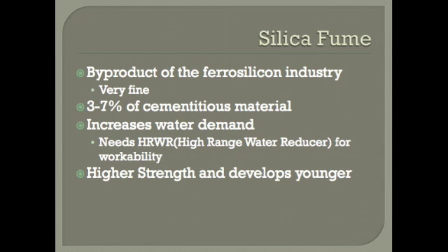Unlike fly ash, silica fume increases the water demand. This results in the need for a high-range water reducer to allow for workability. This high-range water reducer is fairly expensive and increases the expense of the pervious concrete.